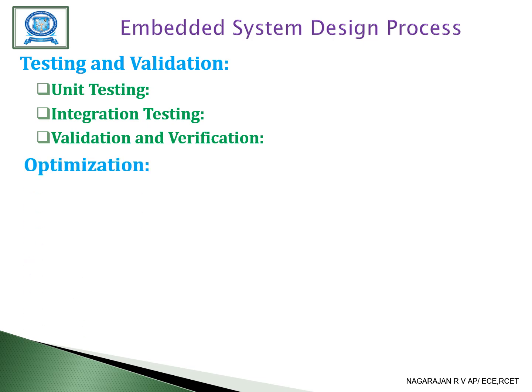The next process is optimization. Under this, the first one is performance optimization. The system performance is fine-tuned by optimizing code, improving hardware efficiency, and reducing latency. Performance optimization techniques include code profiling, loop unrolling, memory management improvements, and hardware acceleration, that is, using a DSP or FPGA.